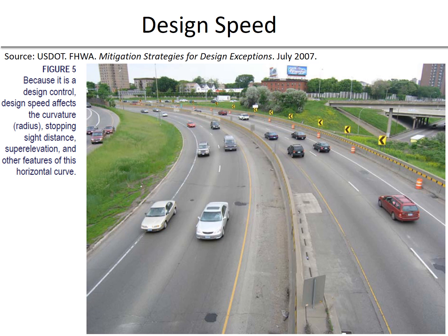This image shows a curve that likely is having some difficulties with drivers understanding the design speed. We can see chevrons in this curve. We can see tape along the barrier here to help alert drivers of the curve. The barrels may or may not be a permanent fixture here to help alert drivers of the curvature.